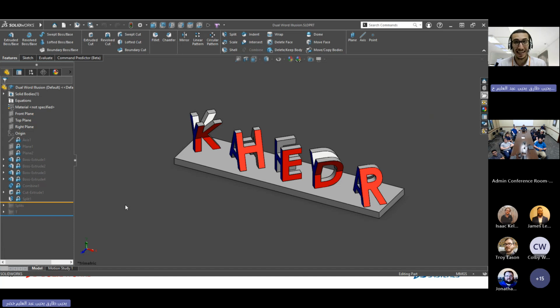And yes, you can animate just a single part, although you're going to be a bit limited in what you can do. So you definitely can't move it around, but you can move the way you look at it. You can also change the appearances, do all of that sort of thing. But it's within reason, right? So anything that you can do in an animation, you can do with a part or an assembly. Both of them are the same thing, other than moving components around, because that actually would need a reference to move it about.